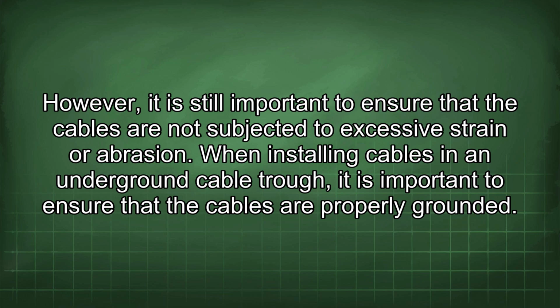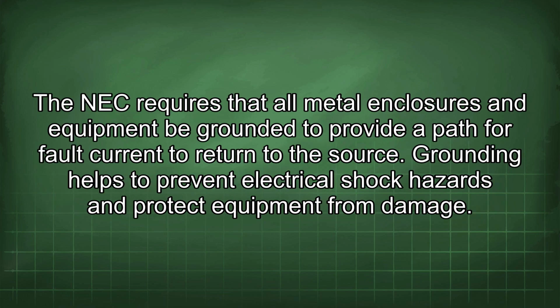When installing cables in an underground cable trough, it is important to ensure that the cables are properly grounded. The NEC requires that all metal enclosures and equipment be grounded to provide a path for fault current to return to the source.